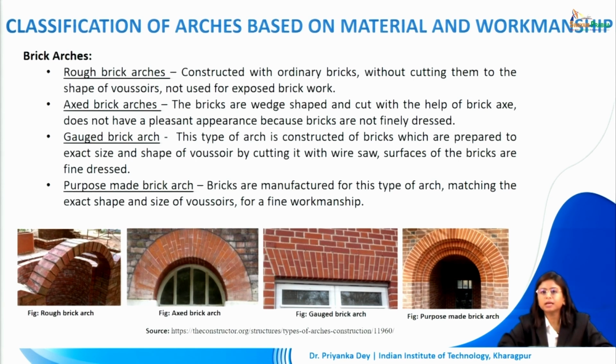Rough brick arches are constructed with ordinary bricks without cutting them to the shape of voussoirs, and they are not used for exposed brickwork. But if we go for axed brick arches, here the bricks are wedge shaped and they are cut with the help of a brick axe, and it does not have a pleasant appearance because the bricks are not very finely dressed.